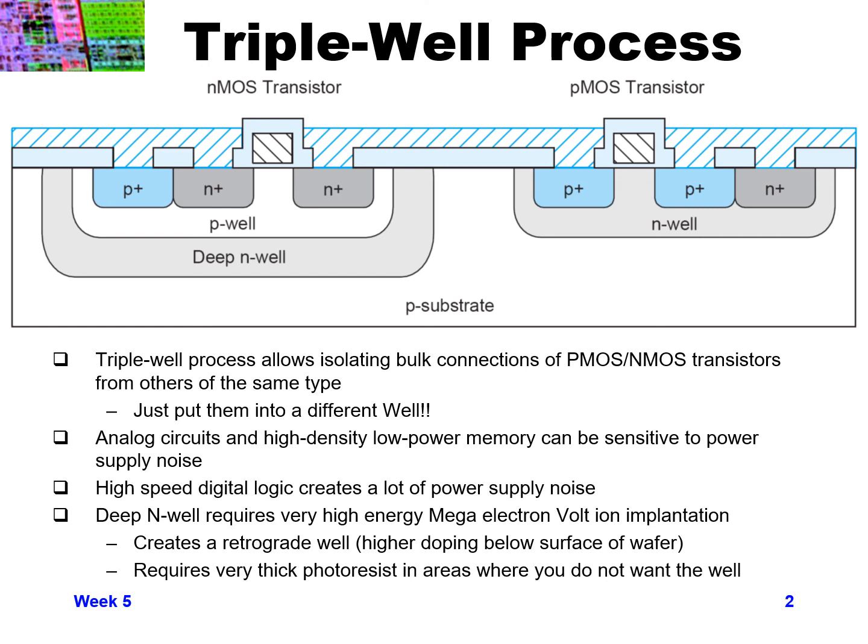Another thing, maybe you want a separate power and ground supply for really high speed digital logic, because high speed digital logic creates lots of noise, and maybe you want that to be on a separate power supply that is not being shared with more sensitive logic.